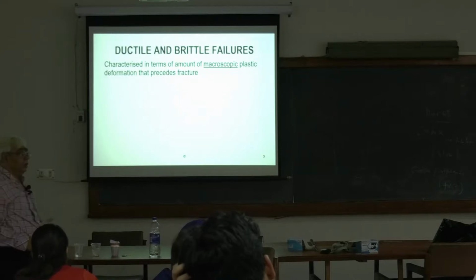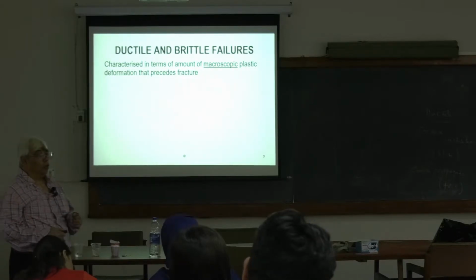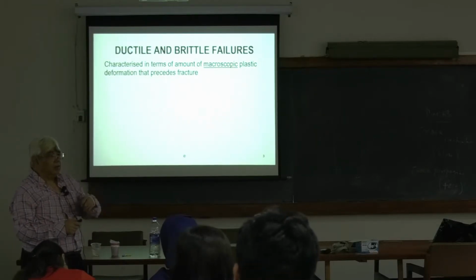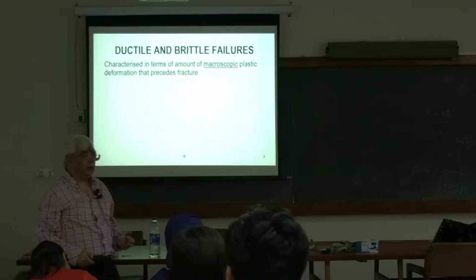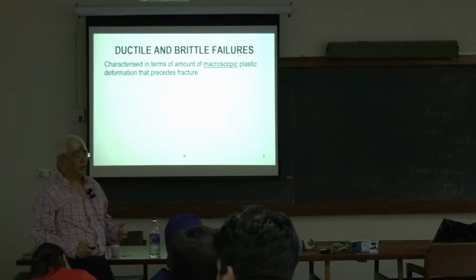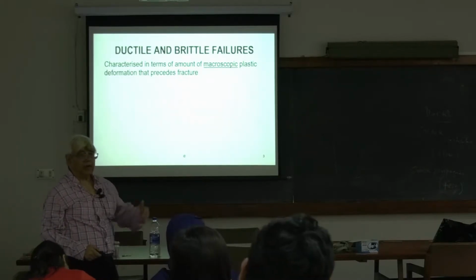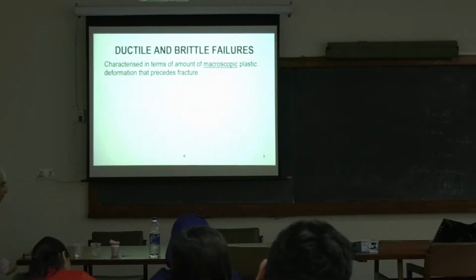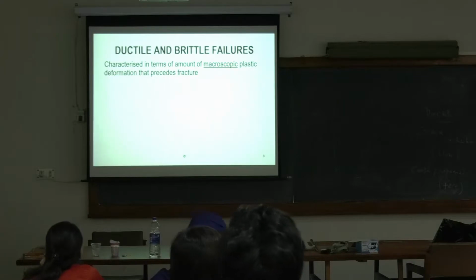So why? That means if you have a good amount of plastic deformation, whatever energy you have given there, whether it is a train, bus, tram, or your own foot, that plastic deformation is taking up all the energy. So the crack is not getting much of the energy. You may have a defect, but the defect is not getting much of the energy. The crack cannot proceed. But if the amount of plastic deformation that precedes the fracture is very low, then it's almost a brittle fracture, or sometimes it's called a pseudoplastic fracture, okay.